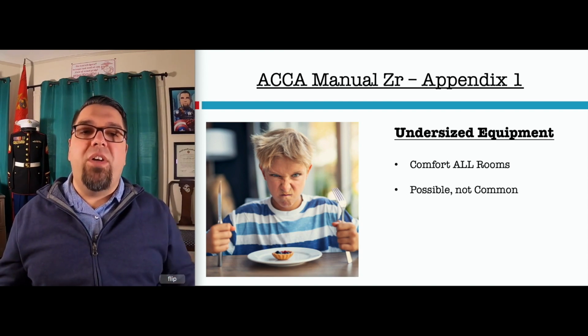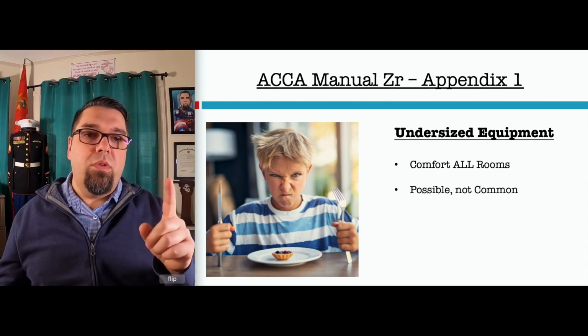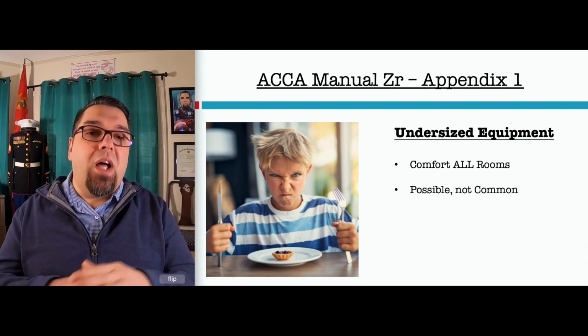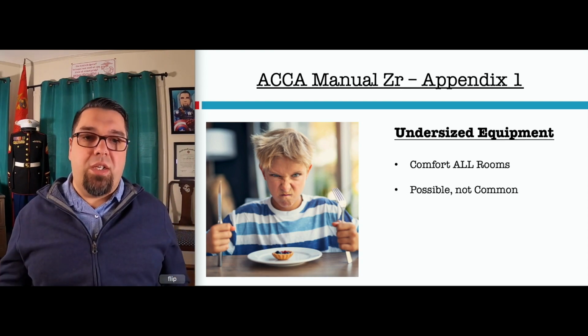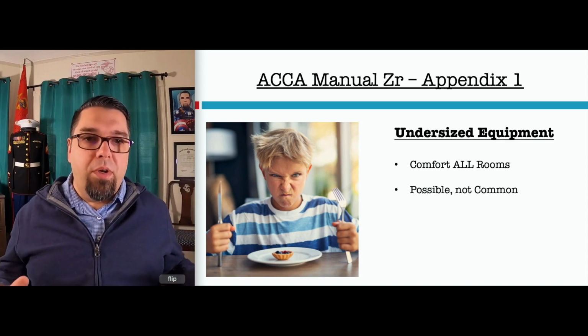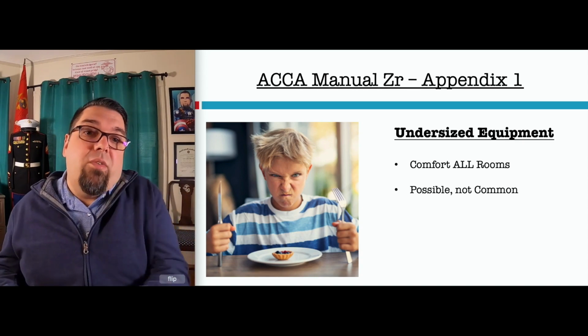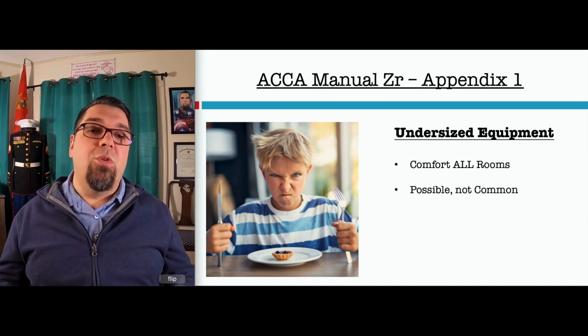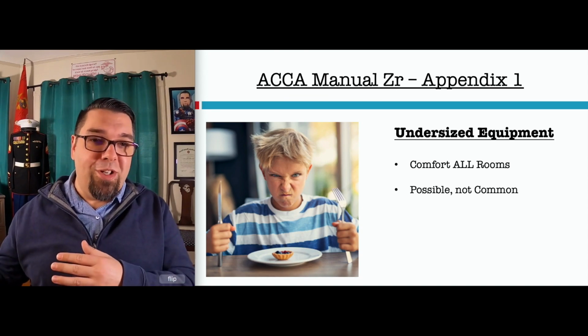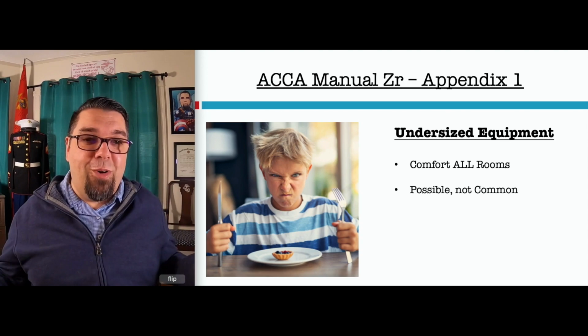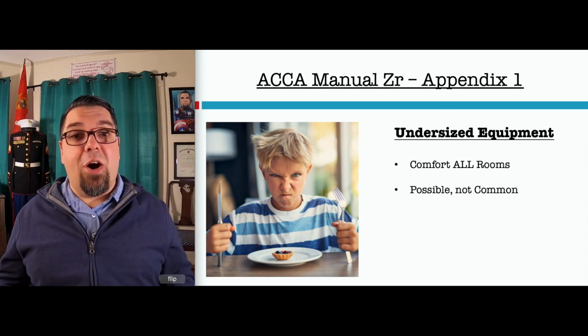That doesn't mean you have undersized equipment if you have uncomfortable spaces. If you have an uncomfortable house, most likely it's undersized equipment, okay? The entire home. And you would have to do another load calculation to verify that. Obviously, I would assume it's somebody else's problem originally that you inherited if it's undersized equipment. If not, we really need to talk about how to do a site survey.